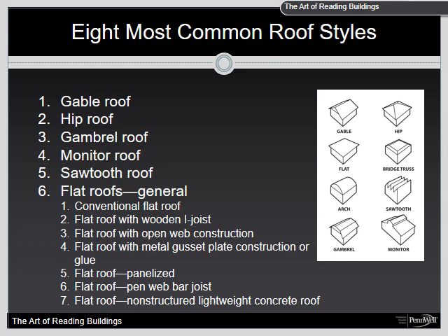The top and bottom chords are usually made from 1/8 inch steel, and the web supports are a solid 5/8 inch steel bar. Large buildings may have bar joist girders spaced up to 45 feet apart. The joists are spaced at 8-foot intervals with corrugated metal decking covered by melted asphalt, and then some type of insulated board, and then alternating layers of melted asphalt and composition. Strength. The strongest area of this roof is at the perimeter of the building.